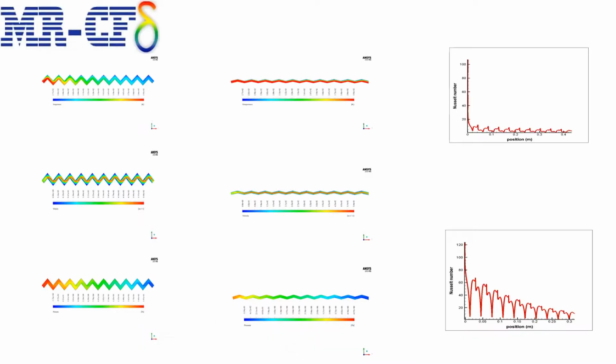After the solution process is completed, two-dimensional velocity, pressure, and temperature contours are obtained for two modes with angles of 15 and 45 degrees. Also, the Nusselt number on the upper wall of the channel along the length for the two modes with angles of 15 and 45 degrees. As can be seen from the velocity contour, the amount of maximum velocity and the average velocity in the case of an angle of 45 degrees are greater than in the case of angle of 15 degrees. It also reduces the rate of pressure drop.